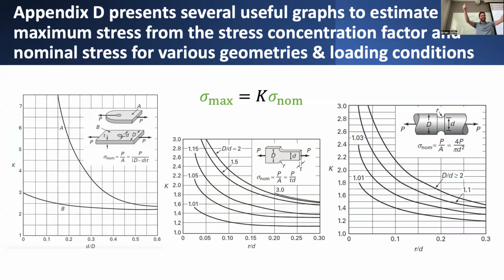There's a homework problem that asks you to figure out the maximum stress that would occur in this kind of elongated plate-like thing. And it seems like, oh no, I have to solve an elasticity problem. It's so complicated. But really, they're asking you to just pick off values from this chart to determine the stress concentration factor for that particular geometry. And then very easily you can figure out the maximum stress. So deceptively simple, but very useful.